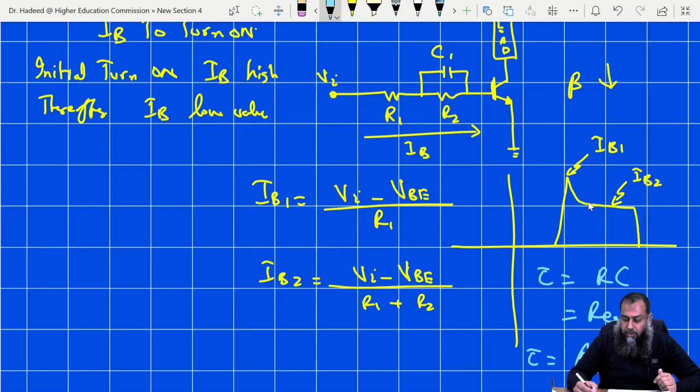And therefore, depending on the amount of capacitance and the resistance, we can set the time constant such that the system comes into a steady state condition before we make any changes in the circuit. Otherwise, if this 5-time constant is not maintained here, then we may not be able to achieve steady state switching characteristics for this particular BJT.